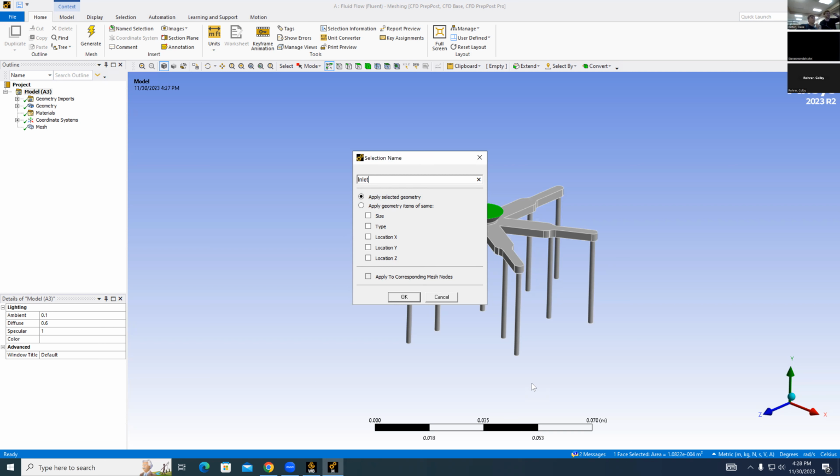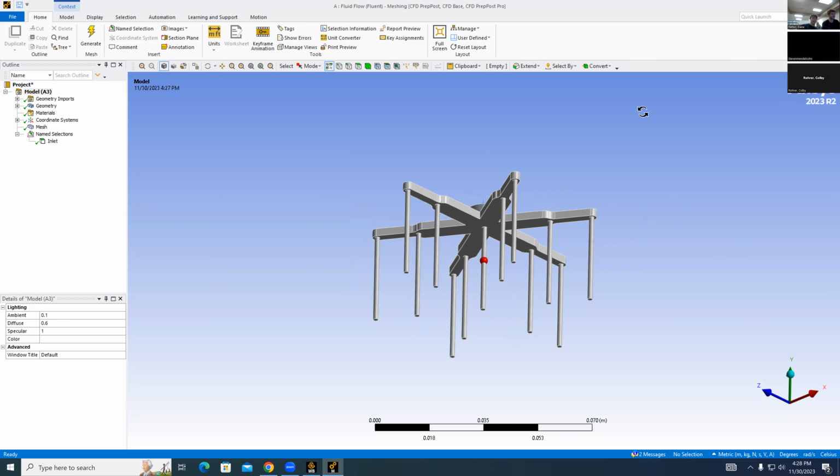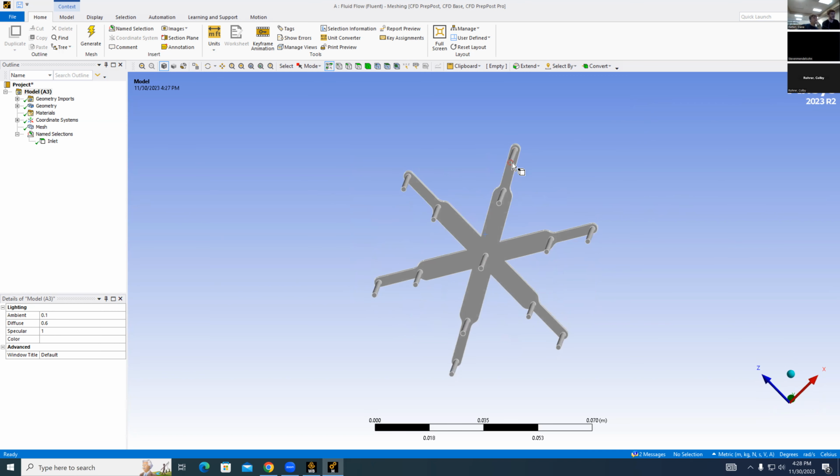When you name them, actually, inlet, outlet, and walls, the program recognizes that you've named it that, and it will auto assign these named sections in our solution generator. You'll want to do that to the best of your ability to keep these names. I used a weird name one time, and I had to dig through it to find it. So just use the right names if you can. We're going to use these later for our boundary conditions when we actually run the simulation. So having those all named just makes it easier. Yeah, you'll need that to be named.